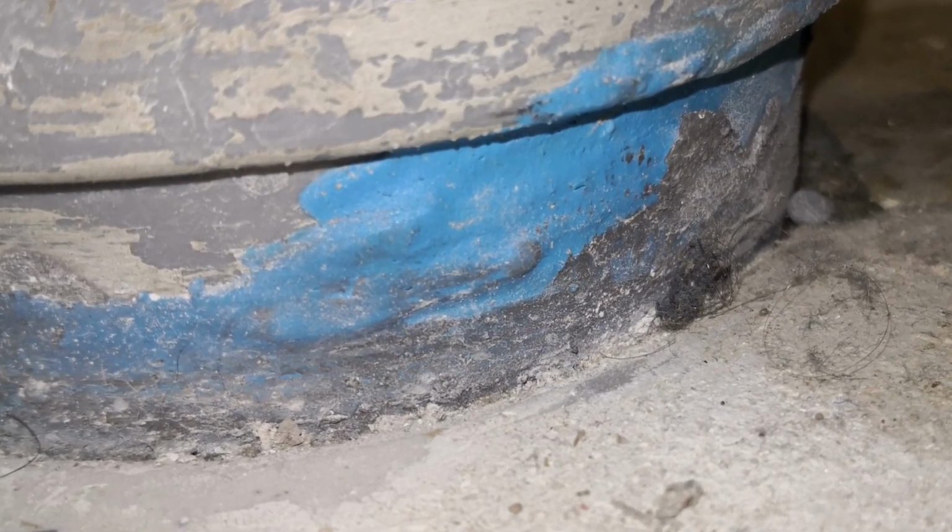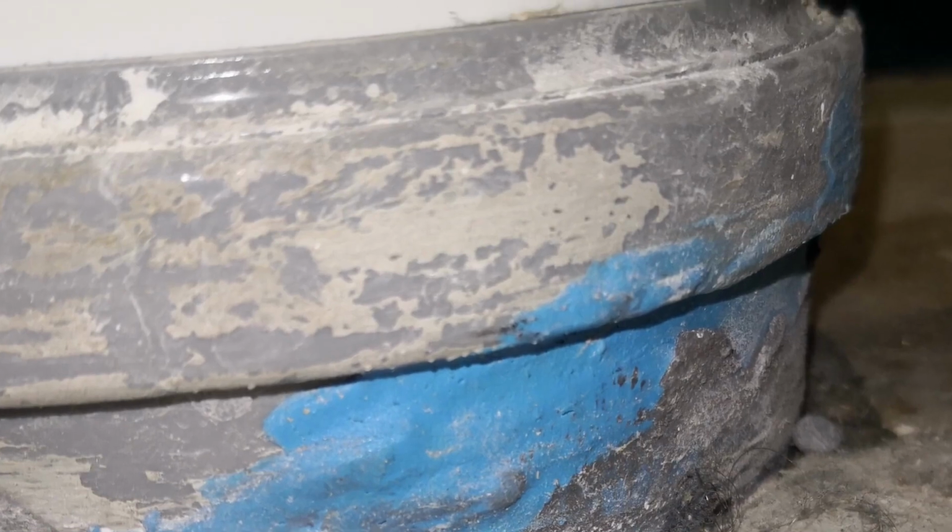The fourth version, leaky connections around pipes and sanitary equipment. In some places, sealant was missing. In others, it was cracked. Water could also have gotten under the tiles through these areas, but the same principle applied here as well. The waterproofing should not have let it pass downward.